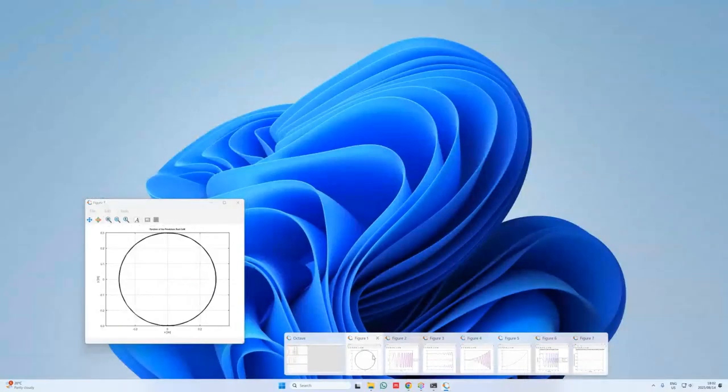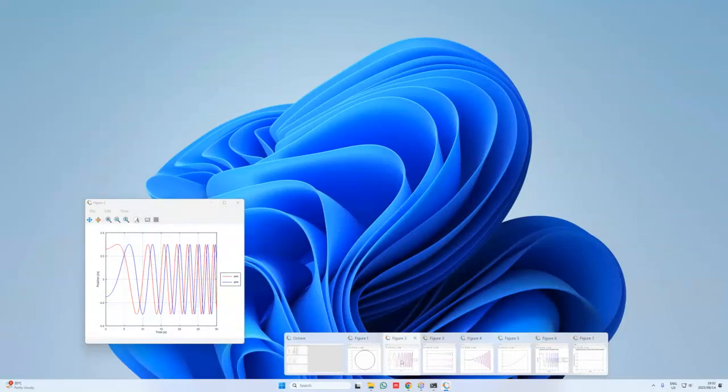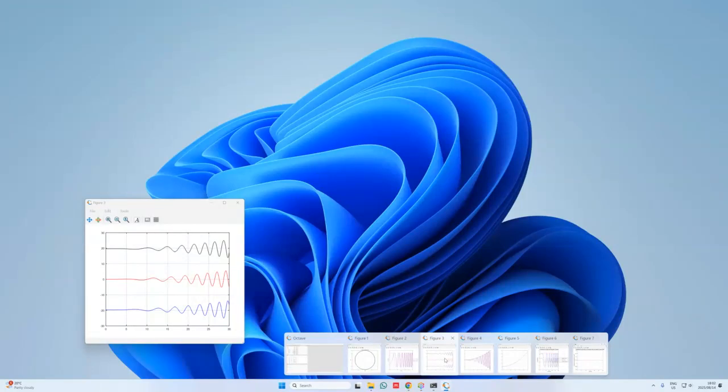Okay, so figure 1 is once again the circular profile of the pendulum rod, so that seems correct. Figure 2 is the x and y coordinates of the pendulum rod center of mass. Once again, oscillatory, constant amplitude, increasing frequency. So that seems more or less the same as what I had previously. Then I have my reaction forces associated with the kinematic joint, or the revolute joint, that I specify for the pendulum rod. I also have the linear accelerations in this case, which also seem more or less the same as the previous case that I ran.